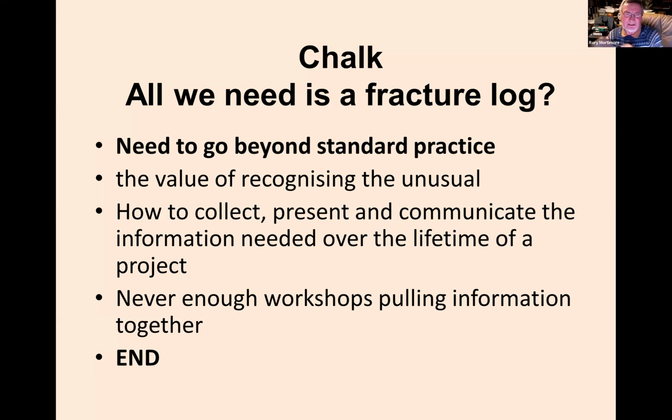And as a result of switching the stress axes, you're getting inclined conjugate fractures developing as a result of almost stretching of the rock along the marl seams. So the marl seams are creating these mechanical discontinuities, allowing the rock to move. Whereas if you've got a homogeneous rock mass, and you're just stressing it vertically, you're more likely to get a standard vertical fracturing because your stress orientations are different.